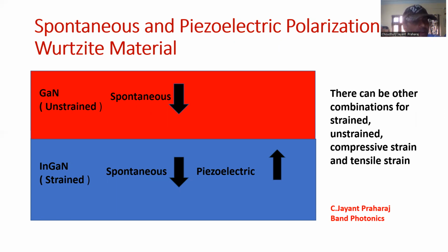And for some of these barriers, the abrupt barrier can obstruct the current flow, and that is what we don't want to happen. So the quasi-continuous grading is a fairly good way of getting over this constraint and to get good photocurrents, good photovoltages, and the best solar cell device performance out of these devices.